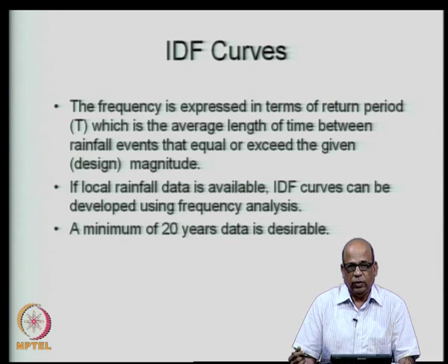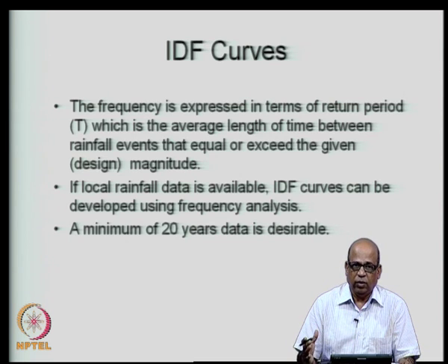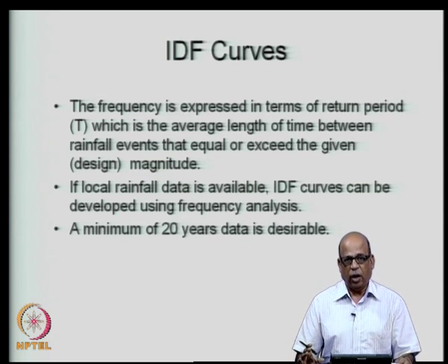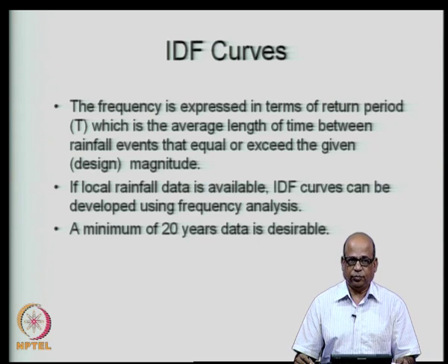So, for a given duration, knowing the precipitation, you know the intensity of rainfall. Then we have the frequency. Frequency, as I mentioned, is expressed in terms of the return period, and the return period is fixed for a particular design, or various return periods can be examined for a particular hydrologic design, based on the engineering judgment and also based on the importance or the criticality of the design itself.